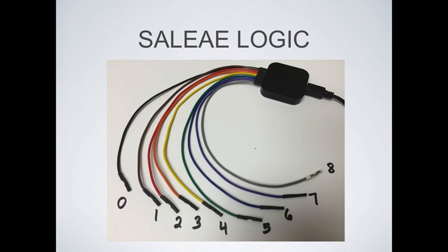So that is where you want to attach that line, to a ground pin on the board. And what that does is it provides the reference. You remember the reference of how far voltage is oscillating from its reference. Essentially, it's the ground voltage.